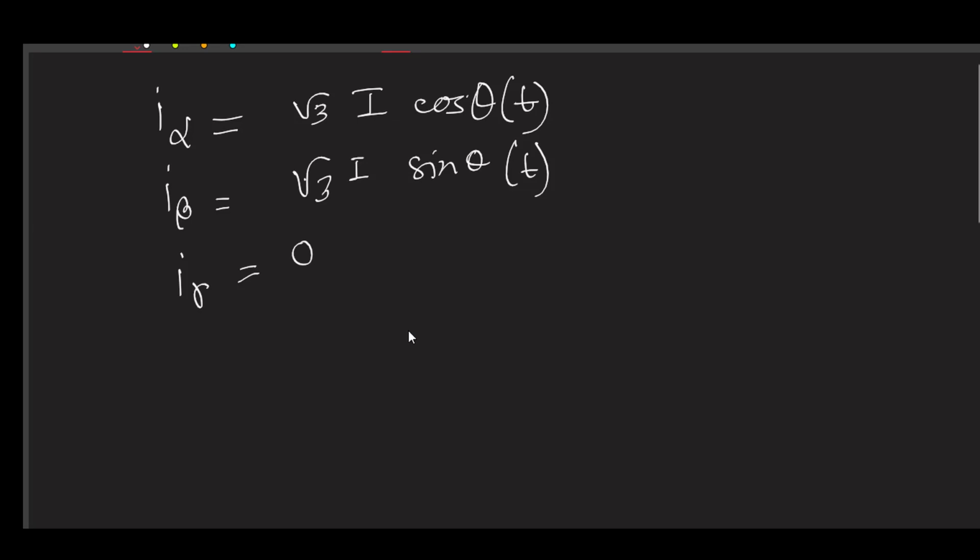well, before going to Clarke, let us have the geometric interpretation also. We can consider that it represents the three-phase quantities onto our two stationary axes, the alpha axis and beta axis. We just convert this three-phase to kind of two-phase without any loss of generality.